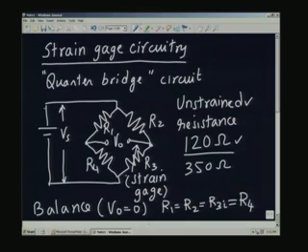If it is compressive strain or elongation, what happens? If it is elongation, the resistance R3 is going to change to a higher value; R3 will increase. This is what we have seen from the basic theoretical framework of the strain gauge, R equal to rho L by A. We have discussed already the way the length is going to change, the elongation, and the area is going to change because of the Poisson ratio. So, we already know this,